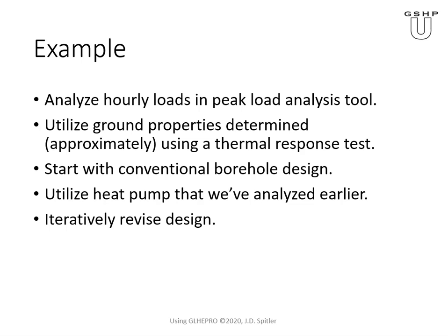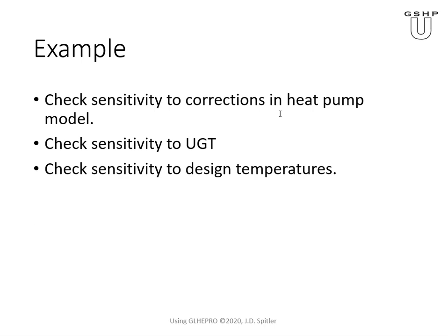Okay, so what I plan to do with the example is analyze the hourly loads in the peak load analysis tool, then utilize the ground properties that we determined with the thermal response test, so those on the last slide. I'll start with a conventional borehole design, and we'll utilize the heat pump that we analyzed in the lecture on modeling of ground source heat pumps. We'll do some iterative revision of the design. And then I plan to check the sensitivity to the corrections in the heat pump model.